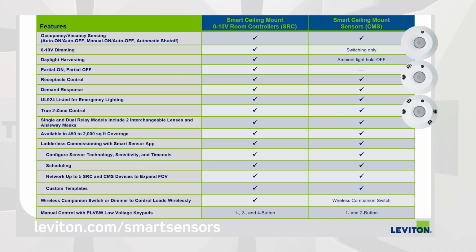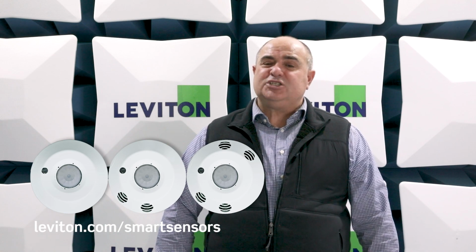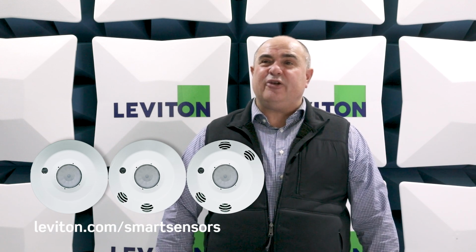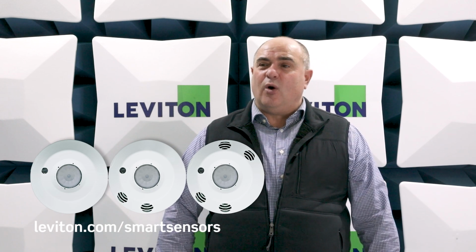How about the 0 to 10 volt dimming? Well, the smart room controller does allow for the 0 to 10 volt dimming. However, the smart ceiling mount sensor only allows for switching of the lighting on and off, which in certain codes, such as Title 24, any room that's less than 100 square feet or less than 0.5 watts per square foot, does not require the multi-level control. And it's becoming more and more standard. We're seeing more and more spaces being designed at less than 0.5 watts per square foot.